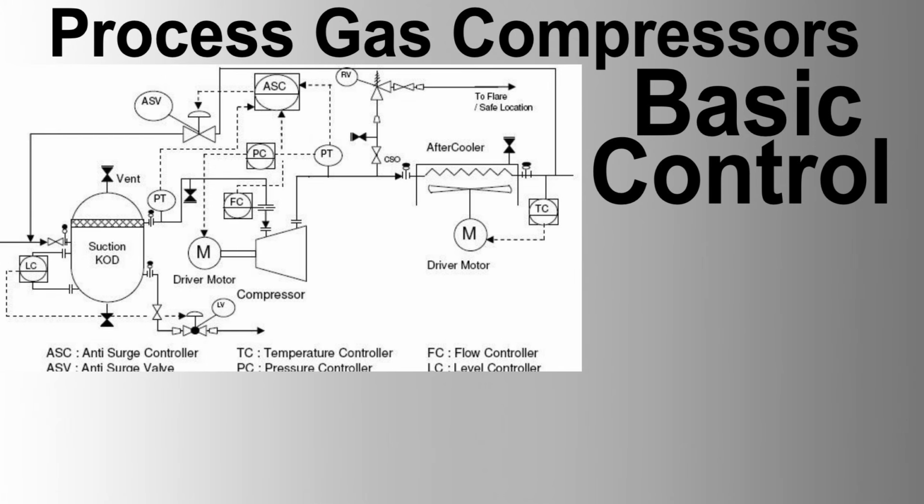5. Vibration monitoring of the compressor. A. Vibration sensors. Accelerometers measure vibration levels in terms of acceleration. Velocity sensors measure vibration velocity. Displacement sensors measure vibration displacement.